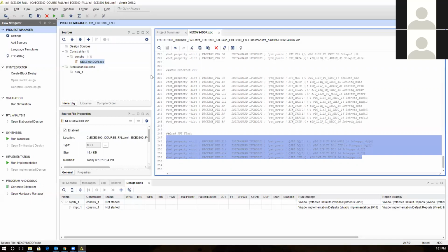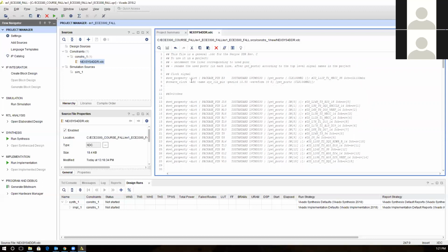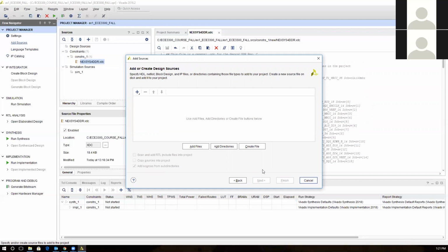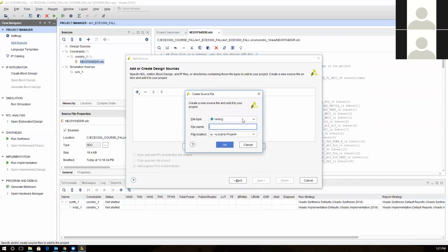Okay, now I'm going to make an example to see how it works, and later on we're going to start talking about the language. So now I'm going to create the design. So what is a design? Next, create, and here in front of you, the types of files I can create vary from Verilog, SystemVerilog, VHDL, and there is something called Verilog header if you are building a library, or memory file if you are flashing a memory. So pretty much, we are now in the Verilog language, so we are using Verilog.